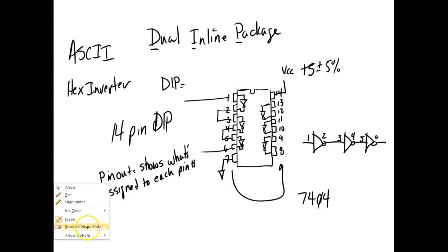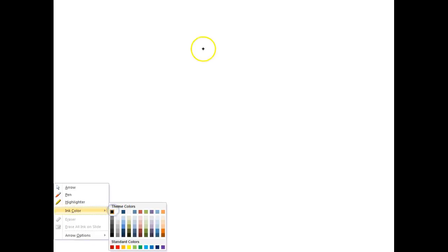So when they originally came out with them, they were all JEDEC registered. So what they did is they started out numbering them. Normally, this is not always true, but normally if you see 74, it means it's TTL. Now that's changed, and we got some weird ones that came out. They'll start off with a couple of letters. These are manufacturer designators.